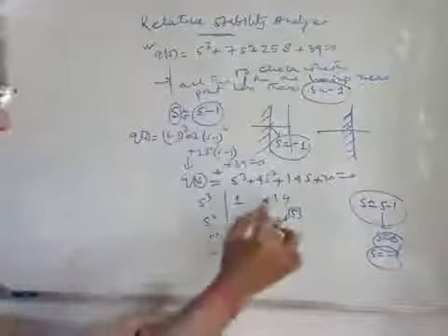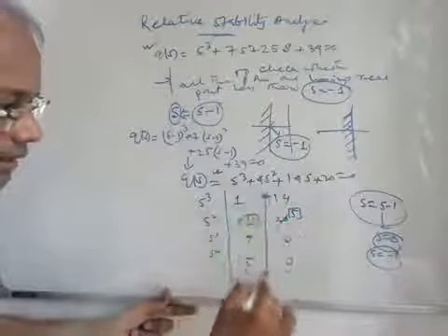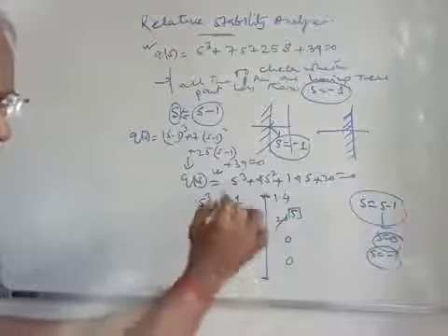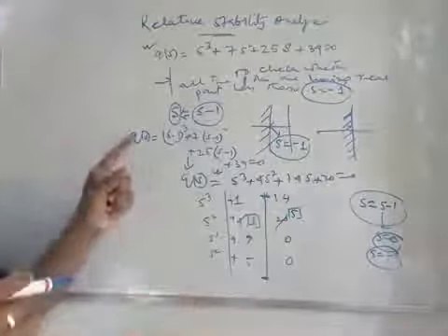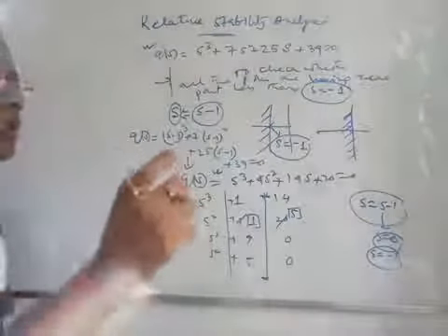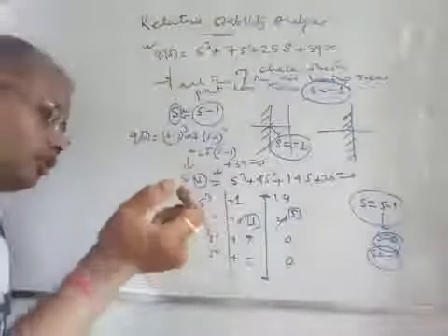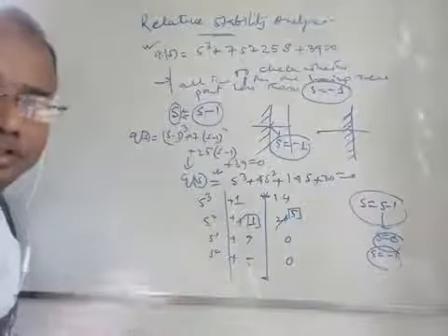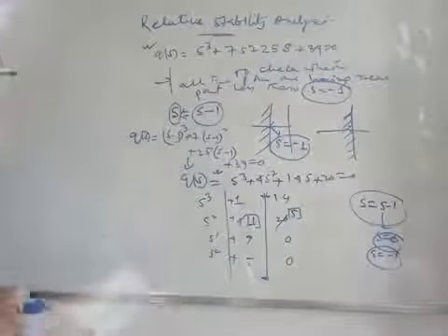So now the system again remains stable because all the elements are positive, right? So the system is stable. That means if you shift all the real poles of the system to the left hand side of s is equal to -1, then also the system remains stable. So this is better stable.